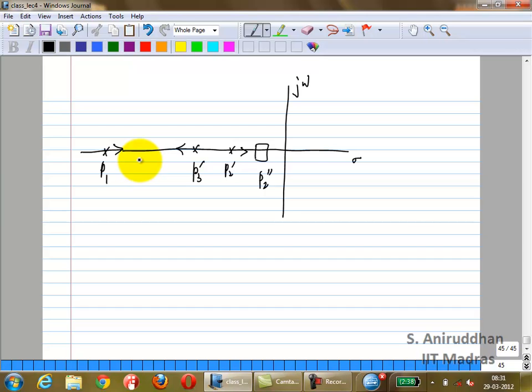What's going to happen? Will they cross over? What usually happens when you have two poles move? You must have studied this in the, I guess, control system. Some of you must be getting to the close, right? So you must have seen something like this. What happens when you have two poles moving towards each other? Exactly. So at one point they'll coincide. After that they'll break into a pair of complex poles.